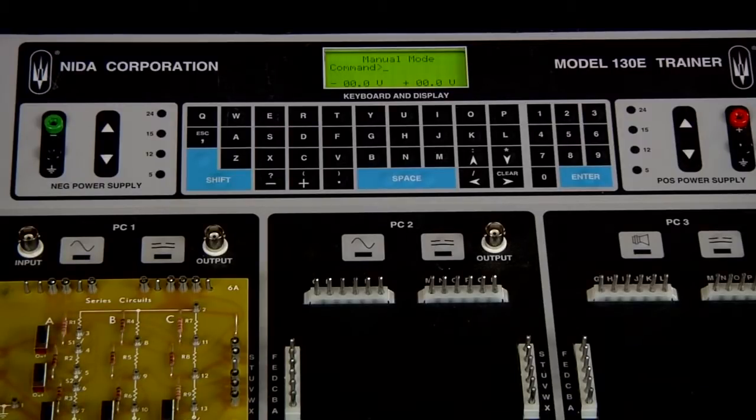If we want to clear the faults out of all the trainer, in other words, out of position 1, position 2, and position 3, we've got basically 2 ways to be able to do that. We can use the C, again, for clear, and then we can just use 0 for the PC connection, and then 0, 0 for the fault number. And that way it will clear all the faults out of the trainer completely.